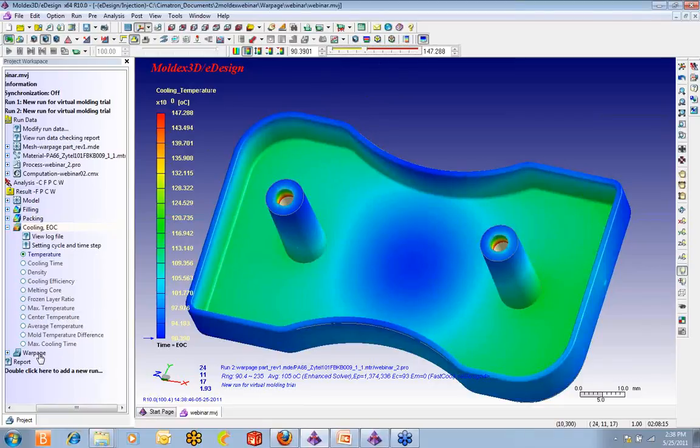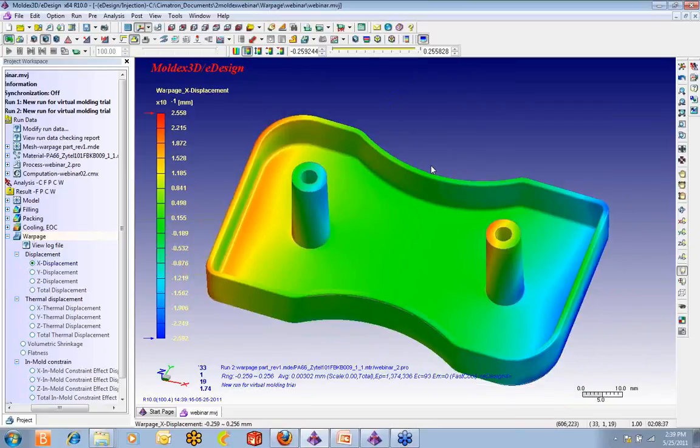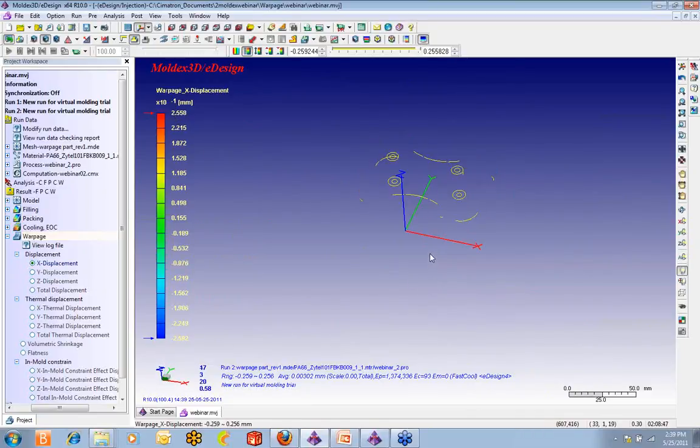And now if we consider what the warpage is like as a result, we'll compare the two. And here we can see that at the worst case, we're at 0.25. So we went from 1.5 mil to 1/4 mil in warpage result. So it's a dramatic difference.